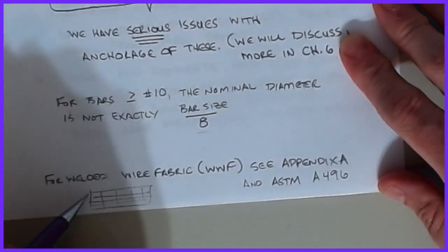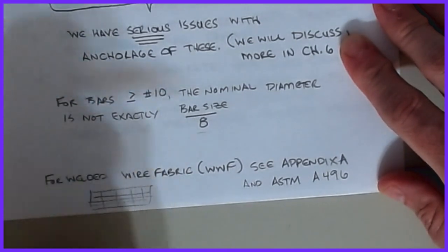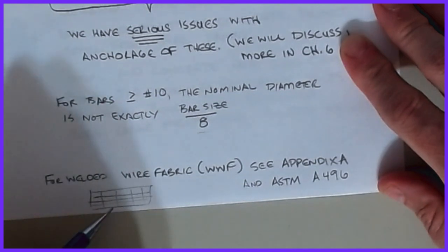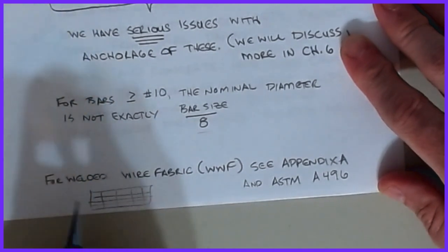So this is very useful in slab construction, and it's specifically very, very useful in the precast industry, because I can drop in a whole lot of bars and it speeds up my fabrication time. Because again, at a precast plant, you're looking to build beams, get the form set up, get the steel tied, get the concrete poured, and then 18 hours later, remove the beam and start the process again. It allows for quick turnaround time rather than having to go in and tie in every one of these bars separately. It's very, very useful.